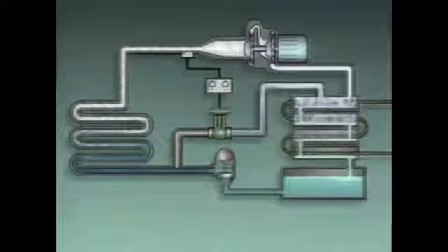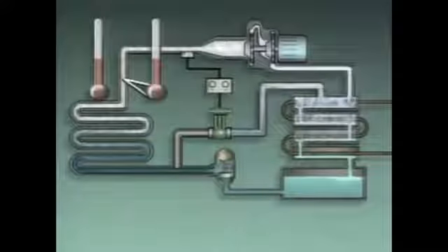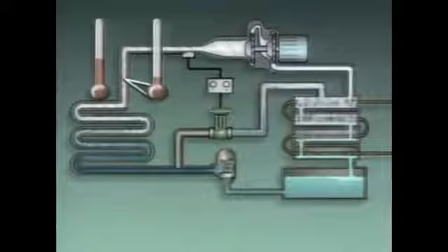The flow of refrigerant through the bypass line is controlled by a control valve to maintain the temperature around the evaporator. If the temperature around the evaporator gets too low, the temperature of the refrigerant flowing to the compressor will drop. When the temperature of the refrigerant flowing to the compressor drops, a temperature sensor sends a signal to a controller, which in turn sends a signal to the bypass line control valve, causing it to open slightly.